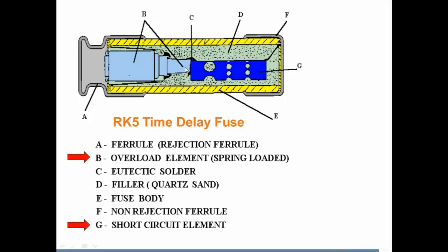And characteristically, and I'm rounding off for the sake of simplicity, the overload segment will activate at 10 times or less the fuse's rating. And more than that, more than 10 times the fuse's rating, the short circuit strip will open without any time delay.